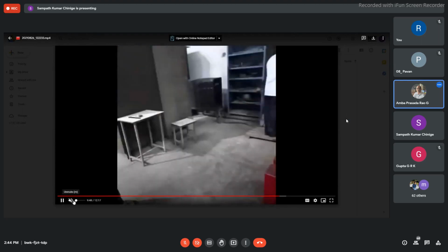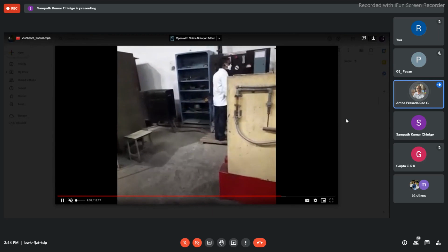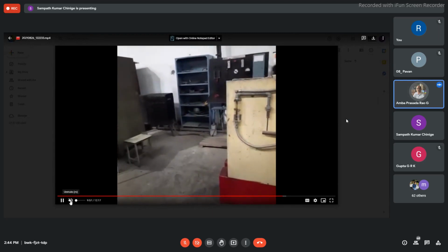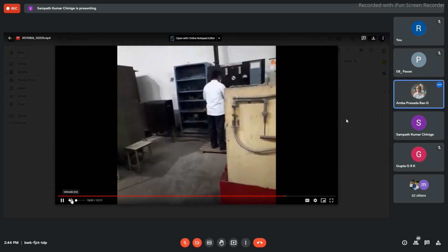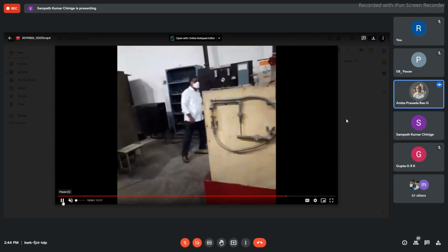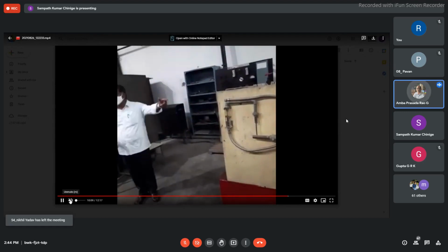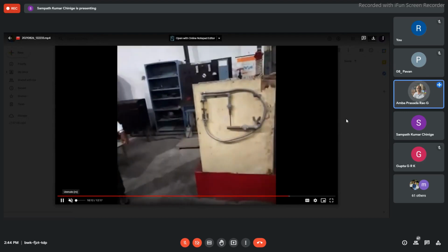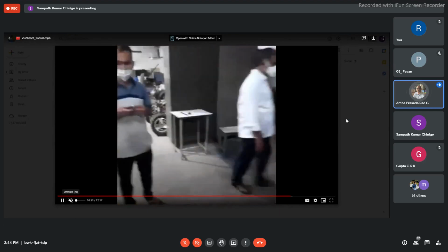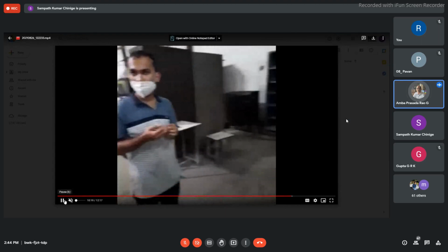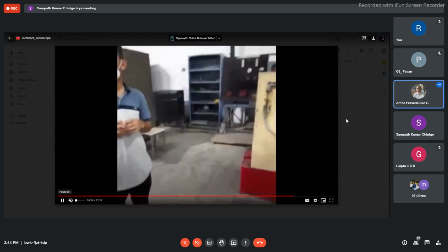Once you go to every step of load, there will be a fall in speed corresponding to the previous load. So we have to compensate for the loss of speed, because our objective is to conduct the constant speed performance test. What does constant speed mean? The engine will be taking the same amount of air irrespective of the load. That is a specialty of a diesel engine, because in the suction stroke only air enters the engine. So irrespective of the load, the same amount of air is going. So what is happening? The air fuel ratio is varying along with the load. Those are all the different derived parameters.